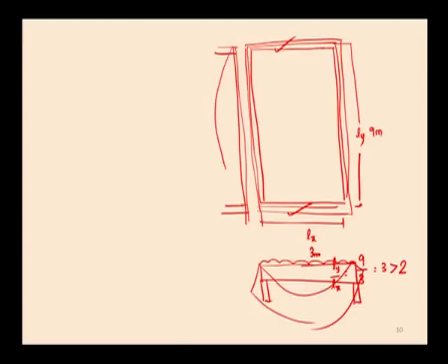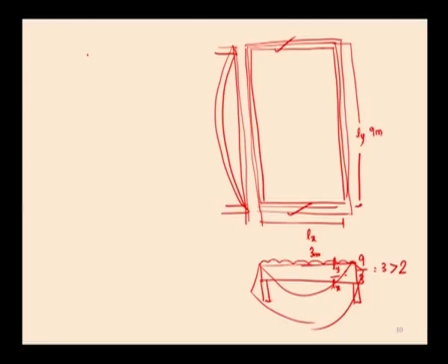There is also a deflection along this direction, but here the deflection along the longer direction is very small when compared to the deflection along the shorter direction. Hence, the deflection along the longer direction is almost negligible and is neglected. That is why the slab has to be spanned along only one direction, that is along the shorter direction, the direction on which the bending is maximum.